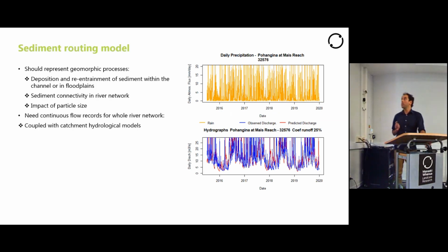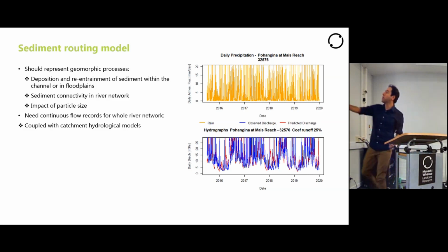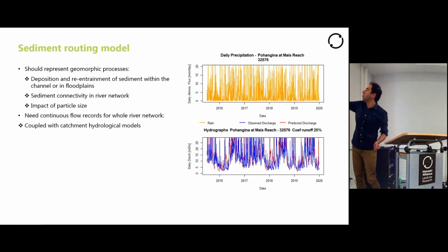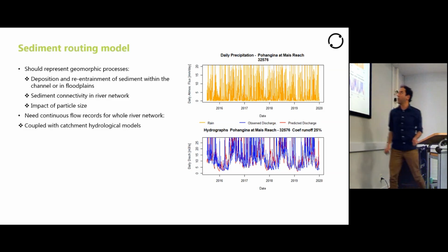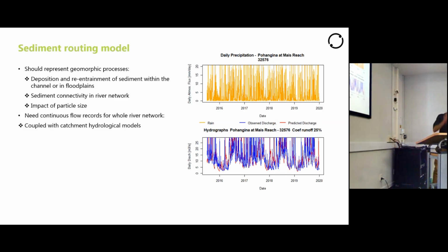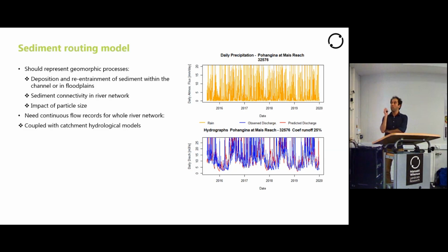However, the model needs a hydrological model on top of that to force the sediment down. For that purpose, we use the TopNet model, NIVA hydrological model, to force as the force of the flow during the flood. So we have the flow data, model flow data for every 3 hours, and then we disaggregate it to 1 hour to use it in the modeling work.